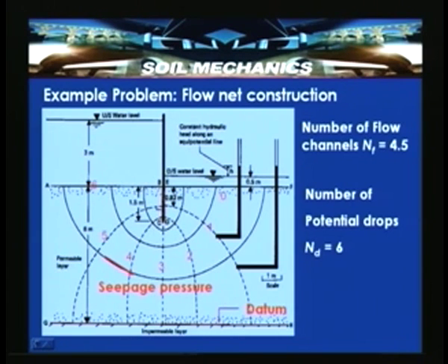This is approximate; it is drawn in such a way that if you insert a circle, you should be able to do it. It is not necessary that all the circles have equal diameters, but we should be able to insert approximately equal circles, so that the curvilinear squares can be obtained.